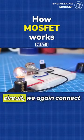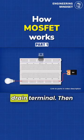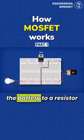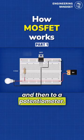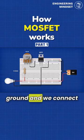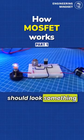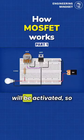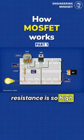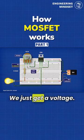For the next circuit, we again connect the 9-volt battery to the lamp, and then the lamp connects to the drain terminal. Then we connect the source to ground. Then we connect the battery to a resistor, and then to a potentiometer. We connect the end of the potentiometer to ground, and we connect the center terminal to the gate pin. The circuit should look something like this. The MOSFET will be activated, so the lamp turns on. The resistance is so high here that almost no current flows through the resistor. We just get a voltage.